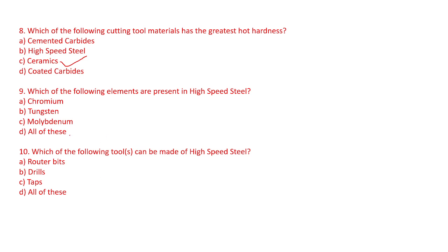So the right option will be all of these. It should have all the components. It is a combination of chromium, tungsten, and molybdenum alloys, and by this combination it improves hardness, wear resistance, and toughness, and also offers a high metal removal rate. So a reasonable amount of these elements or alloys is used, comprising chromium, tungsten, and molybdenum.